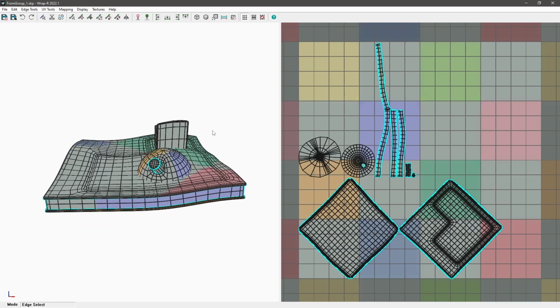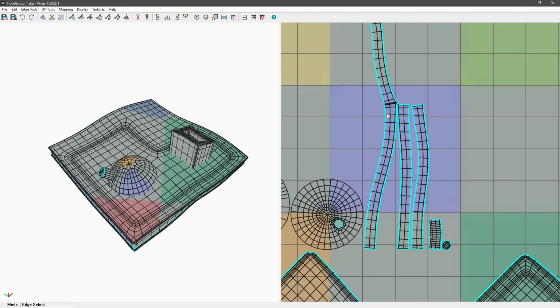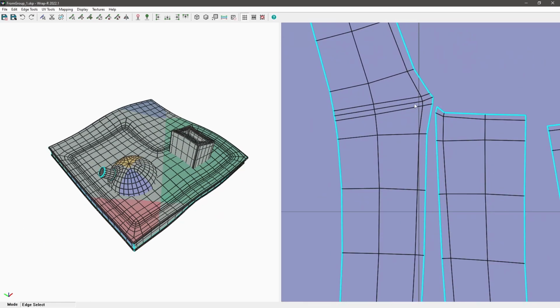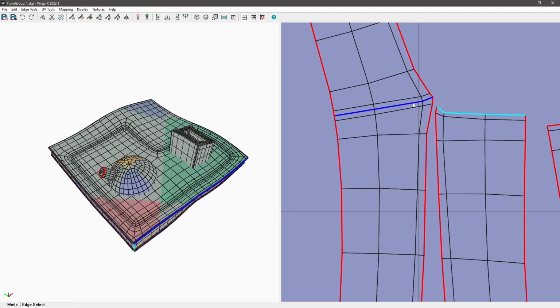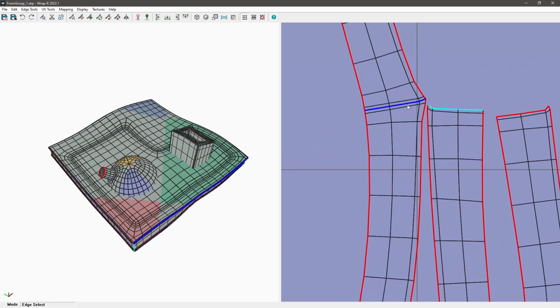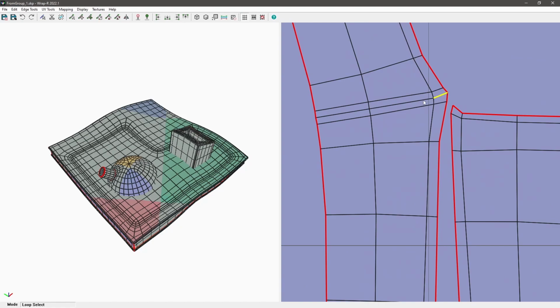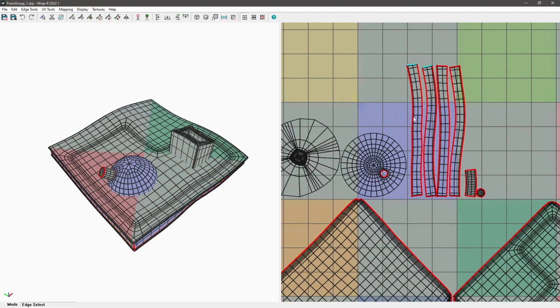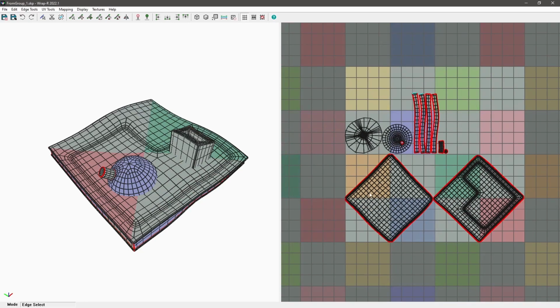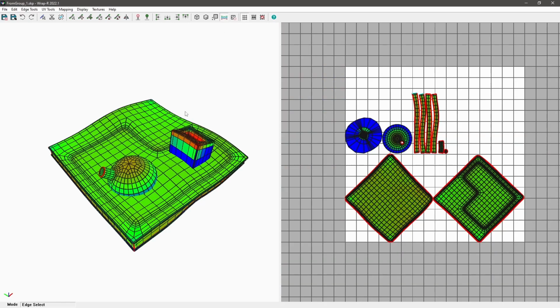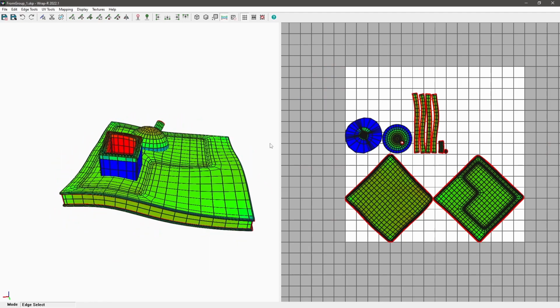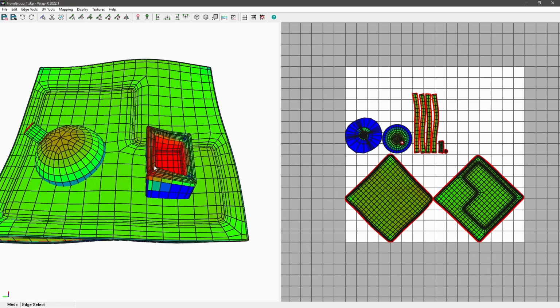Okay, so let's say I want to create some UDIM for this. Oh, I forgot to cut this, so maybe I want to cut this loop. I press T on my keyboard and C for cut. And let's say this is okay, but I'm sure I got some distortion going on here.